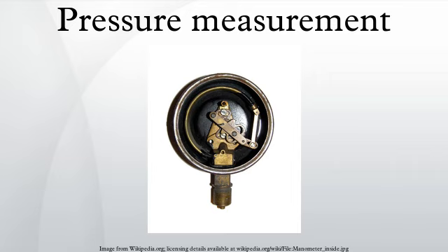Optical uses the physical change of an optical fiber to detect strain due to applied pressure. Potentiometric uses the motion of a wiper along a resistive mechanism to detect the strain caused by applied pressure. Resonant uses the changes in resonant frequency in a sensing mechanism to measure stress, or changes in gas density, caused by applied pressure. Thermal conductivity: generally, as a real gas increases in density, which may indicate an increase in pressure,